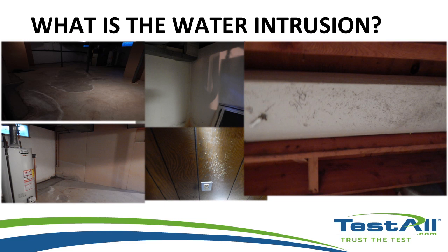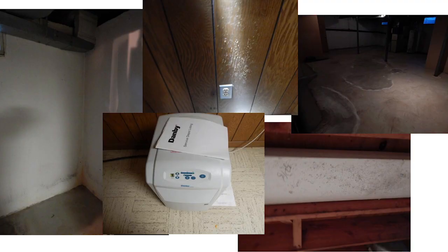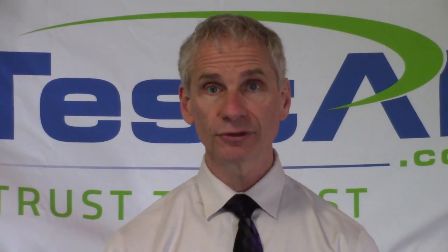We also look between the floor and the wall and you'll notice that a section of the floor has been cut out. And they put in a new drain system there and then put the concrete back on top. However, this sheetrock was put on top of that, so there's an indication that this problem is still occurring. Probably a high water table. When you look at the walls, you don't see any signs of water on the walls. It all seems to be coming up through the floor, an important distinction you need to learn to make.